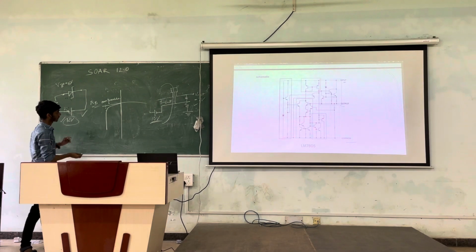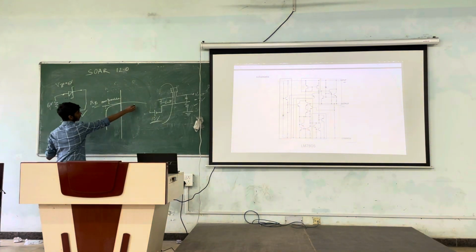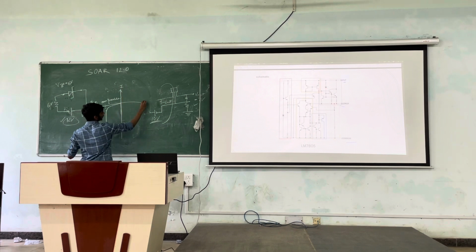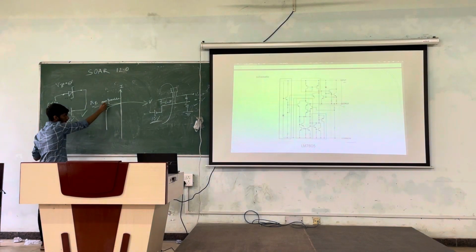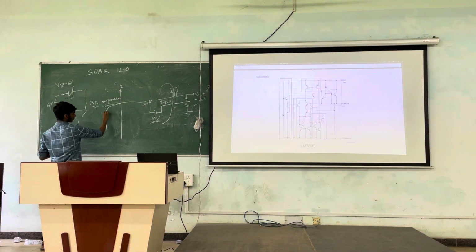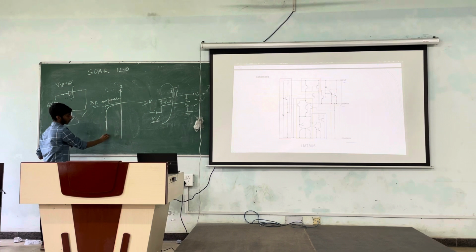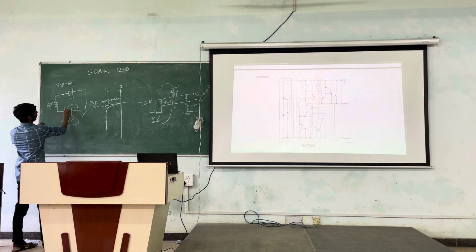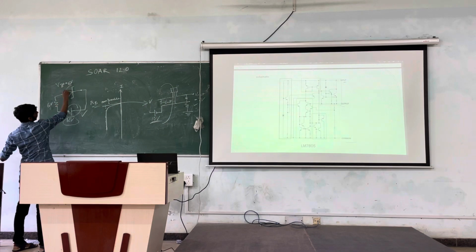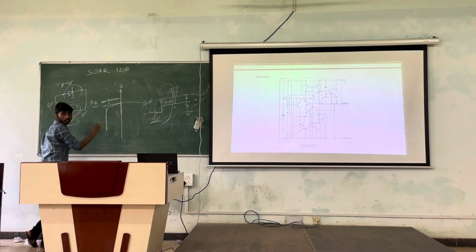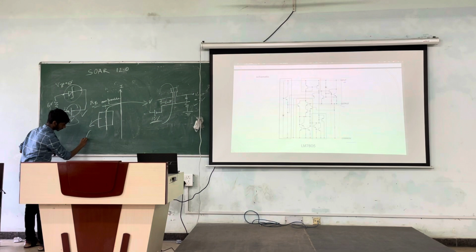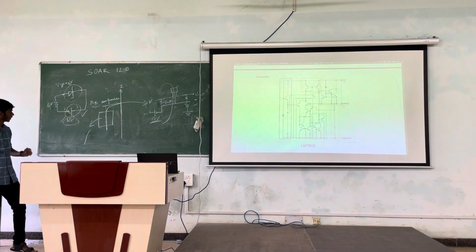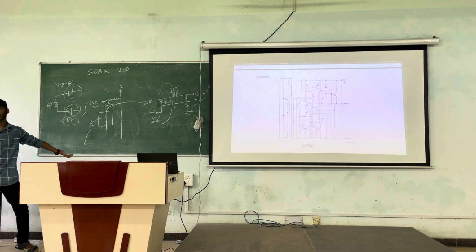If you see, this axis is current and this is voltage. Voltage is getting constant; we are getting a vertical asymptote-like thing here. Voltage is constant and the current rises. As we apply more voltage, the current changes, but the voltage across this diode will still remain sort of constant. But if we zoom in, it still changes a bit. So this is not that stable.